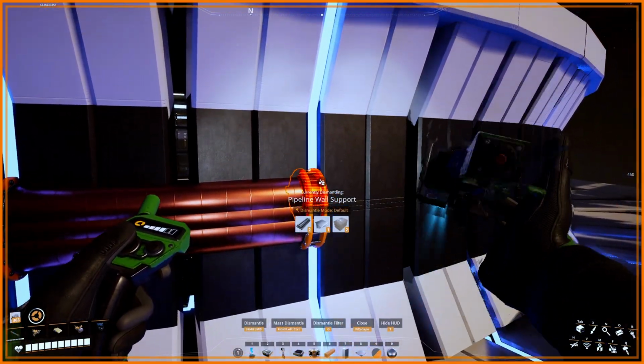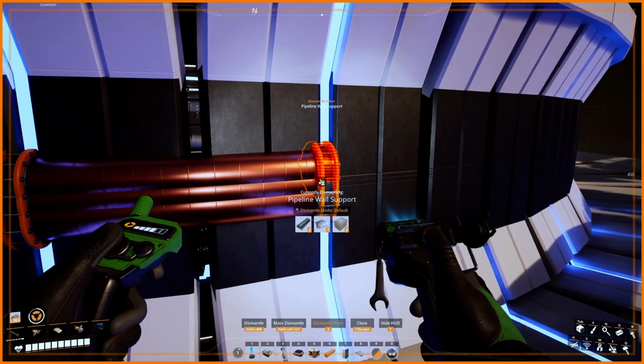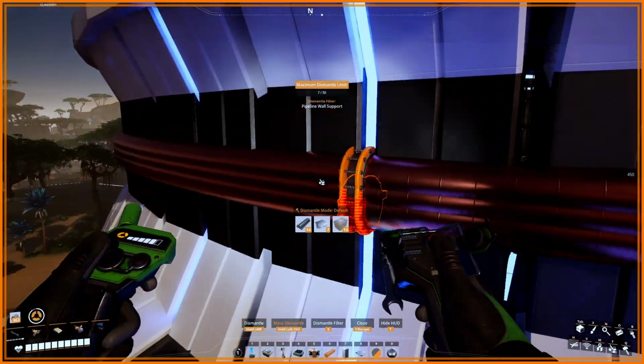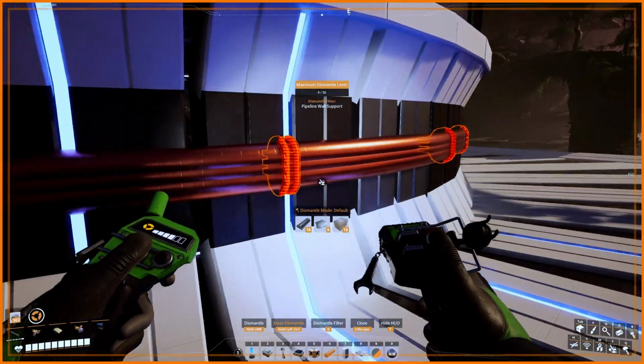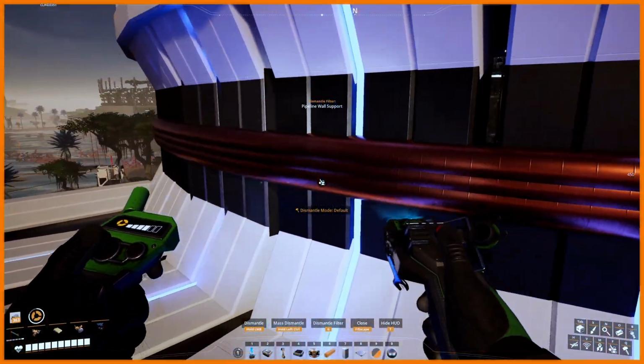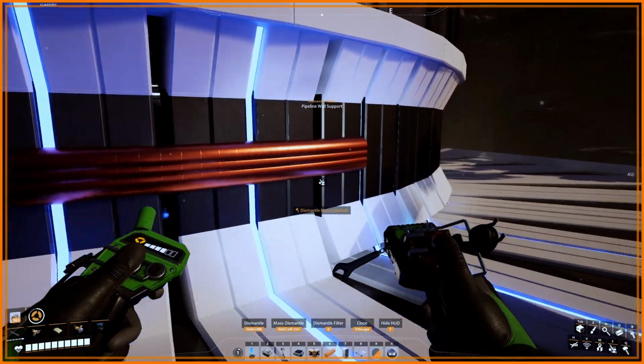So you press F, okay, I'm going to choose that one, and then you press G, and if you now hold Control, you can only target those. So it's a quick way of selecting something that might be a little tricky to select. Right, so once you delete these, there you go. We've got this nice little curve going all the way around.